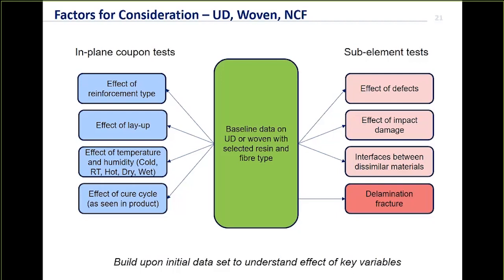and there's a number of considerations when you start to try and do testing that is relevant to your structures. So, for instance, you may have a particular layup in your coupons, but within a structure, particularly if there's some multiple curvature within it, the orientations between the fibres may have a continuous variation over the structure. There are a lot of other things that can have an influence on properties. For instance, the degree of cure. Curing can also leave significant residual stresses.